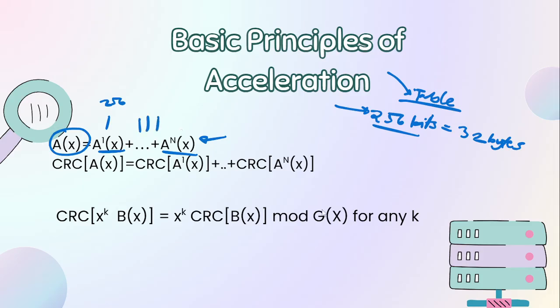The next one, the next one, all of them would be written as 256 bit words. Then we would sum them up, each byte lane, and make the whole word. The math works out so that the CRC of this summed up function, or the whole word, is the CRC computed over each word and summed up.